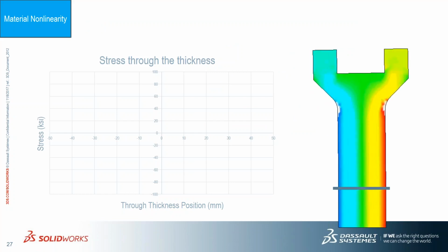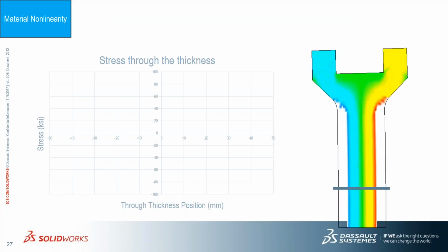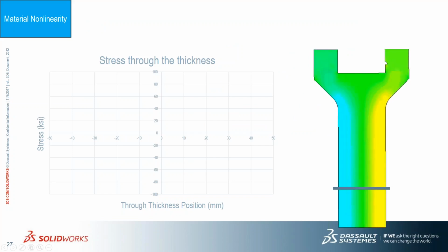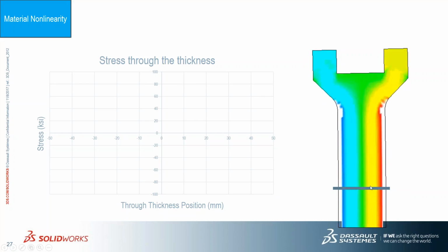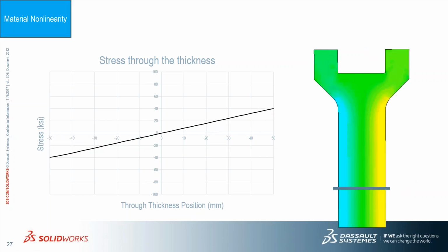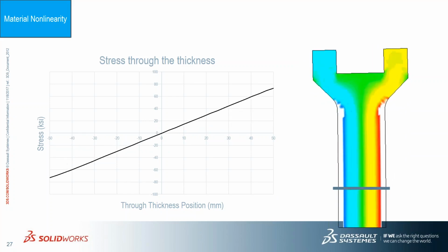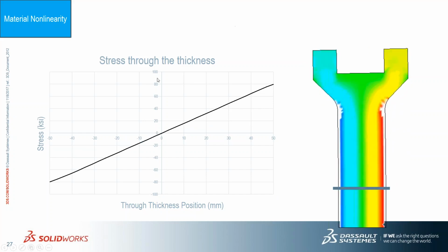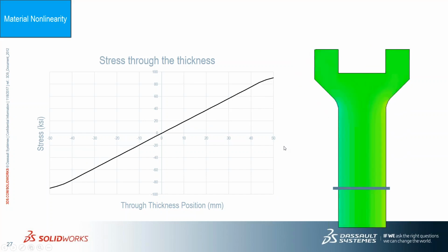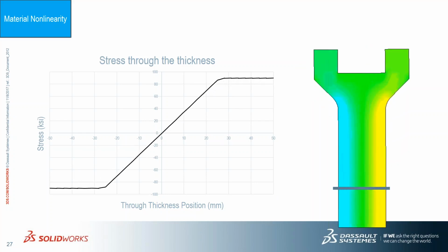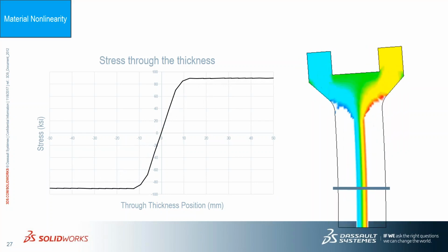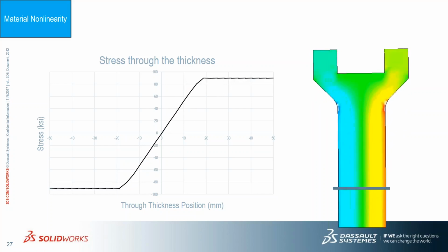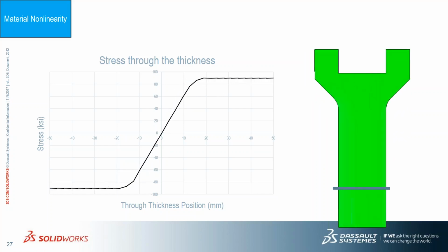So here's an example that shows some yielding, which is using that stress strain curve. The region on this wrench that I'm bending, you see this big white region, that's the yield region here. And I'm going to look at the stresses that develop through this thickness here, negative and positive bending stresses. They'll look something like this. Pretty simple, linear growth of the stress, predictable, up until we get to that yield point, which in this case is around 90. Once I get up to this 90 mark for the stress, it'll start yielding. And then the relationship gets more complicated, or nonlinear. So a static study, a linear study I should say, cannot account for this nonlinearity.